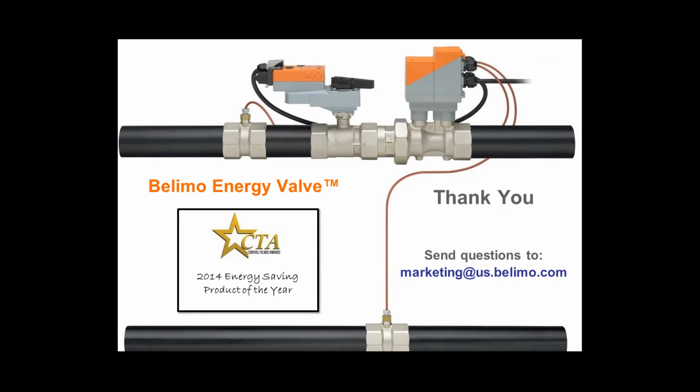So the water is going to hit the flow meter first, and we're looking for 5 pipe diameters before the flow meter, just to get a little bit of laminar flow coming in there. It helps the accuracy of that flow reading. There's no requirement on the downstream side. In my picture on the left side, once that water goes through the ball valve, it's all mixed up anyway, so there's no sense in putting straight pipe after it.